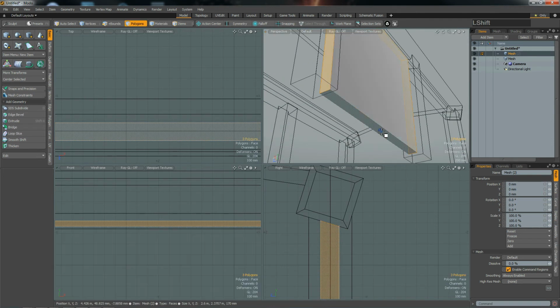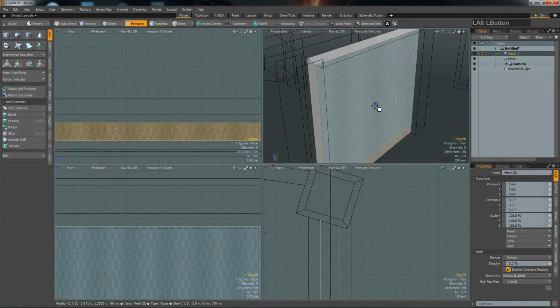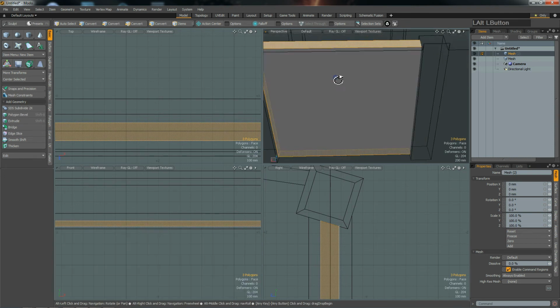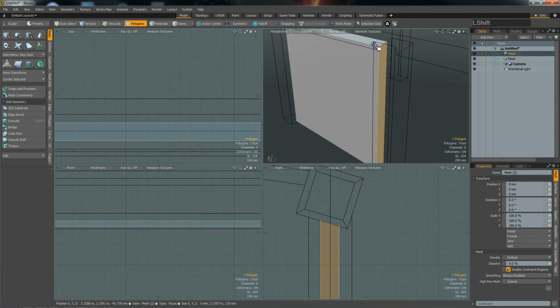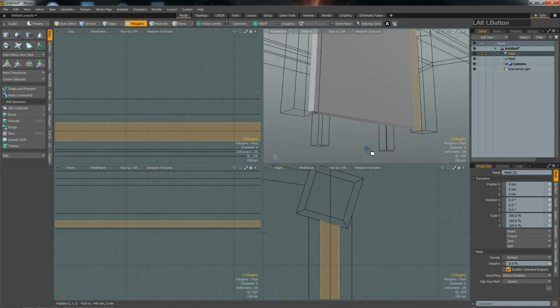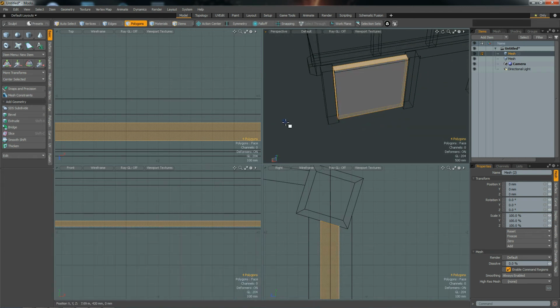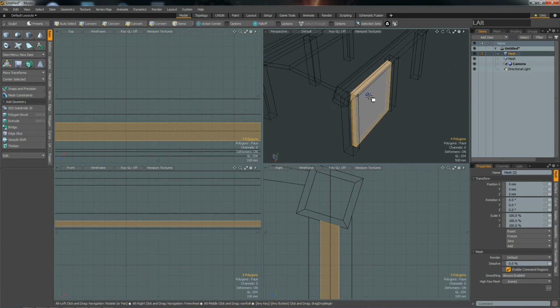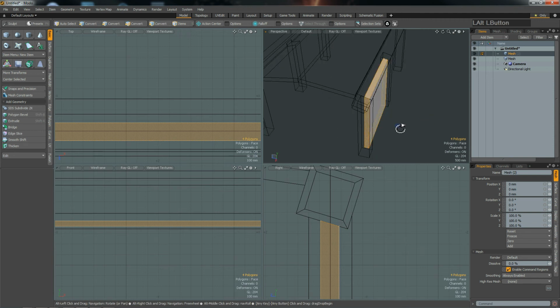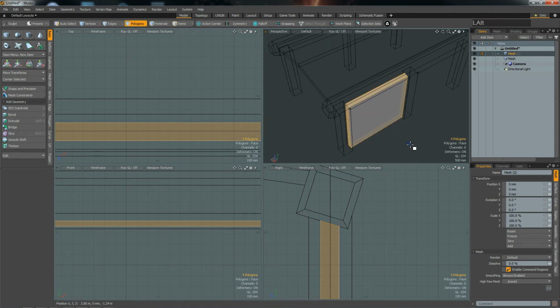Now we can remove all our edge faces, and I can select them all four like this, or if I select two and press the up key on the keyboard, Modo will follow along and select all the edges around a certain object. So if you have a large complex object and want to just select a strip of polygons once around the object, then you can do that very easily. You can even select patterns, and if you then hit the up key, then that pattern selection will continue like this. So you can also have it select only every second polygon, but we're going to look at this later anyways.